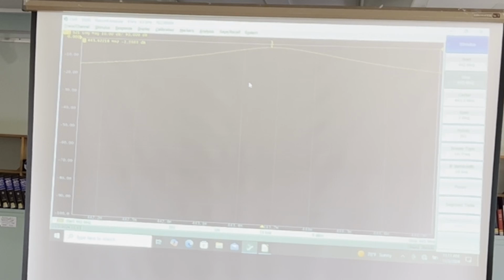What I would do here is set the marker for my desired frequency. Let's add another one. So let's set this one for, what did I say, 443.725. Okay, so that's my number 2 marker.